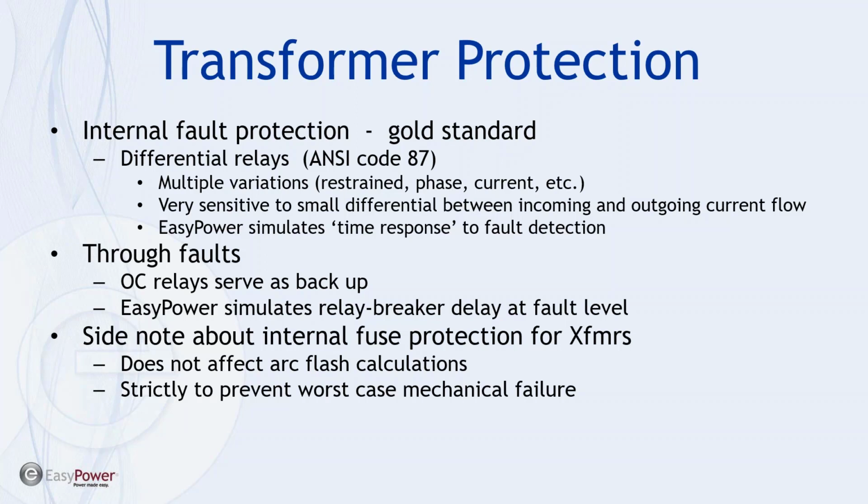Then as a backup for this gold standard, very frequently most systems will utilize phase overcurrent relays as backup, and this is a more traditional TCC plot utilization. We will go through the setup of a phase overcurrent relay and how that serves to protect both for through faults